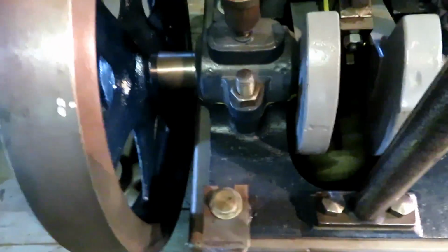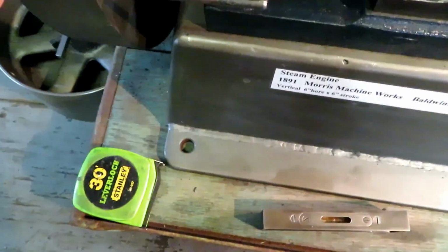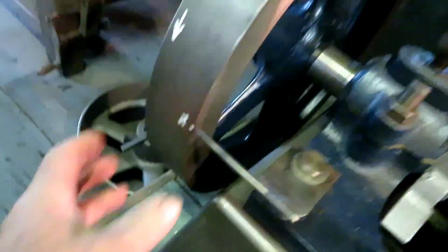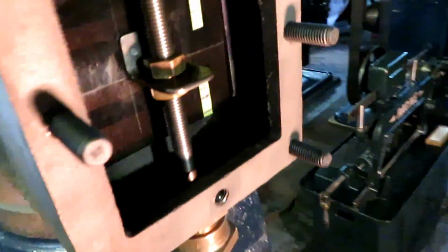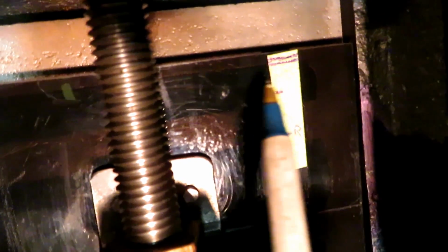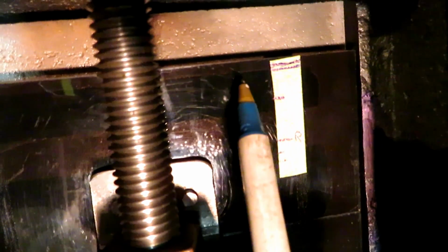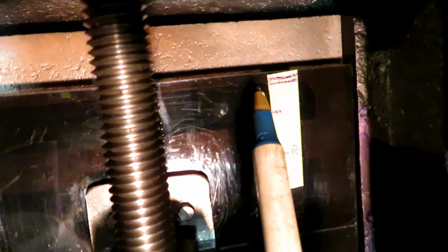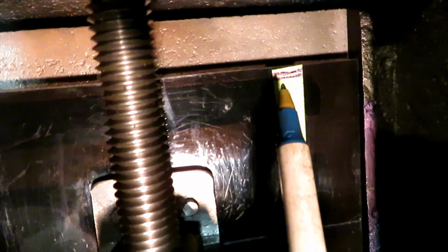But if you put it up on top dead center, make sure, yep, top dead center, my valve being actually longer than it needed to be, I made a mark right there where I can see the edge of that port just underneath the plexiglass, actually down a 1/16 of an inch from the edge, because that's the lead.